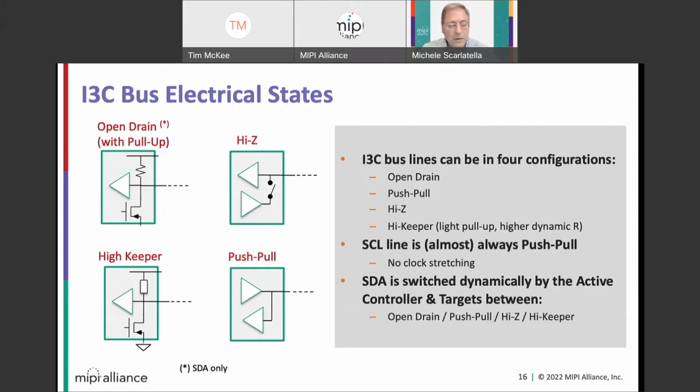There is the usual open drain, which will need a pull-up resistor, or an active pull-up, which is needed in some cases, and it's also there because of the I2C compatibility requirements. But not only that, in some cases you need to arbitrate the bits and so on. So that's the way to do it.